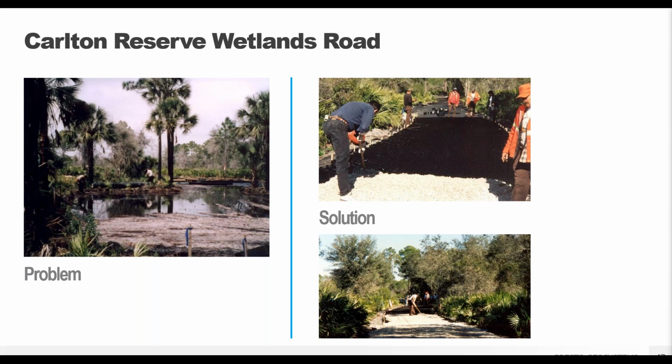And by using a slightly deeper cross section of the base rock underneath the road and parking area, the GeoWeb system was able to retain nearly 3 inches of stormwater per event. So that greatly reduces the runoff potential, and for this particular site, meant that an above ground retention pond was not needed. So huge cost savings there.